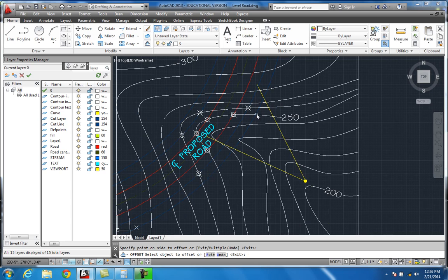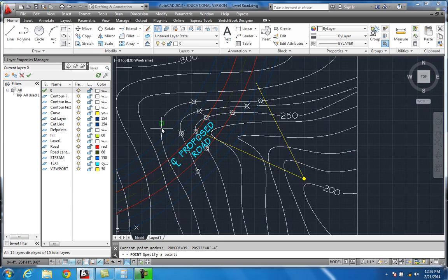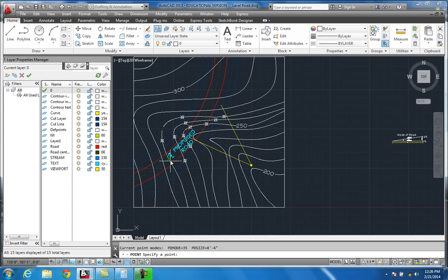this next line is going to represent our 270 contour. So there's 250, 260, 270. So go up here and grab your draw point. 250, 270 is right there. You see where they intersect? Where that one intersects. Zoom in close, make sure you get dead on the money. Follow that line around. This is my 270 line. Click on that. Follow that around. Right there's 270. Just continue.